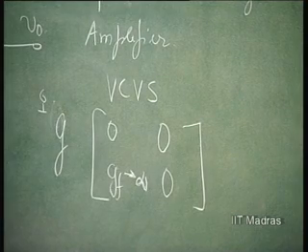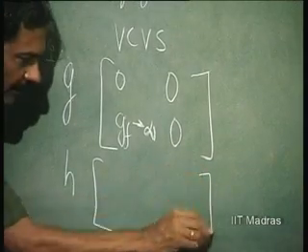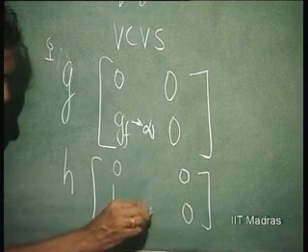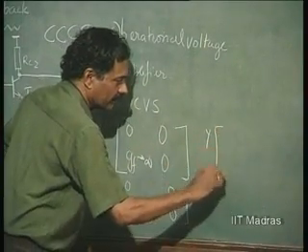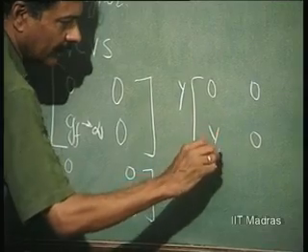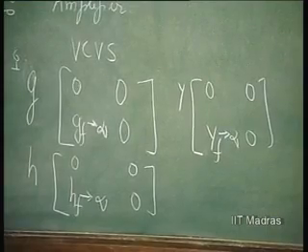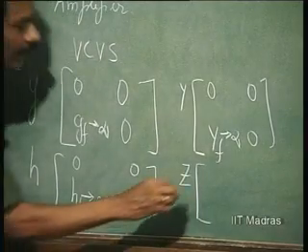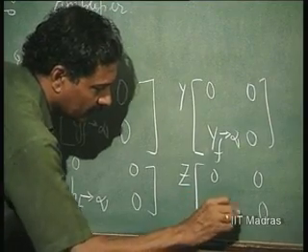If it is a current controlled current source or a current operational amplifier, then you have H parameter of concern. This is 0, this is 0, this is 0, and Hf goes towards infinity. If it is a transconductor type of amplifier, okay, then the Y parameters are the ones that have to be taken, which is 0, 0, 0, and Yf goes towards infinity. If it is transresistor type of amplifier, that is the Z parameter is what is talked about, and here this is 0, this is 0, and this is 0, and it is Zf which goes towards infinity.